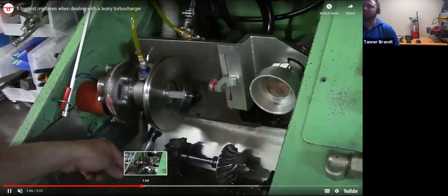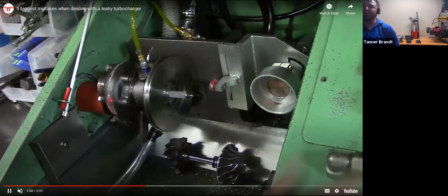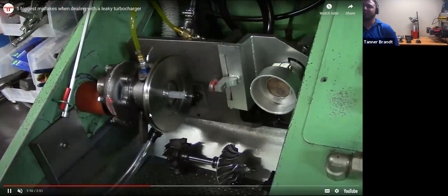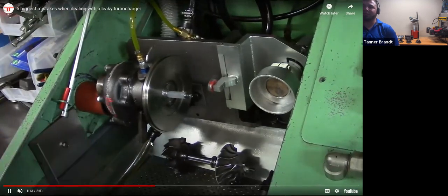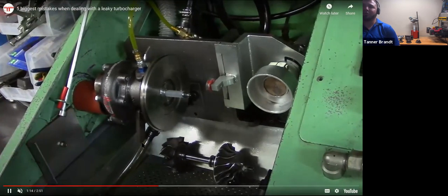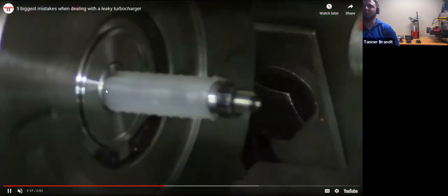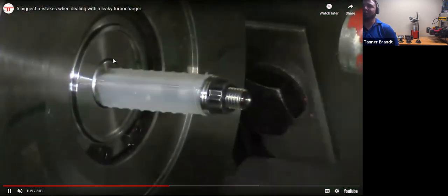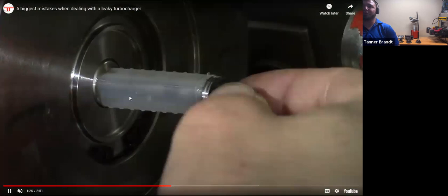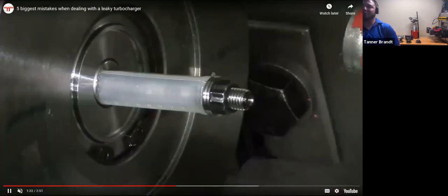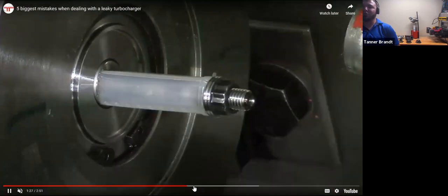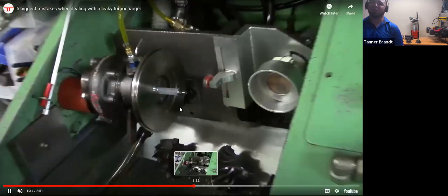So this is the drain tube on it, and oil is going to come up through here and then flow through it. So you can see the oil coming out of it right now. You can also see that he's got no oil coming out from the flinger, even though there's no metal ring in there right now. So the next thing he'll talk about is going through and showing what can happen and what can cause some oil to go out.